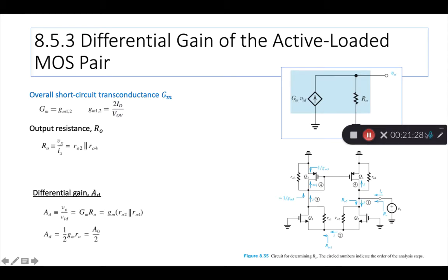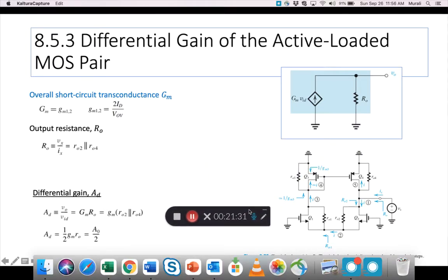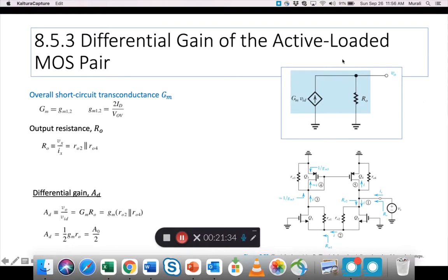So to help us with that, to do the analysis, we first start by creating a model of our differential amplifier, a very simple model, right? There is an input Vid somewhere here, and this blue stuff is the differential amplifier, right? With the whole Q1, Q2, Q3, Q4, everything together. So whatever is the input, it first gets converted, in this model, into a dependent current source.